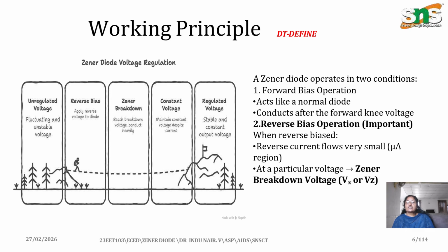And there is another effect called the avalanche effect. For voltages generally above 5.5 to 6 volts, the breakdown occurs due to collision-driven charge carrier multiplication, otherwise known as the avalanche effect, which has a positive temperature coefficient, unlike the Zener effect's negative one. Voltage regulation: because they maintain a nearly constant voltage Vz across their terminals, even with varying current, they are used to maintain stable voltages.